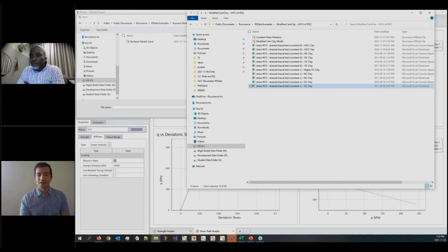Okay. Any further question? Yeah. Go ahead. Yes, on how the cells are organized in Excel and how we can bring it into RS2. So for the rock side, for example, the triaxial, whichever way, the format is sigma 3, sigma 1. So if you paste from that sequence, it's automatic. You don't have to do it column by column. The most important thing is to look in RSData, see how the columns are organized in Excel the same way, and it's straightforward. Copy and paste.